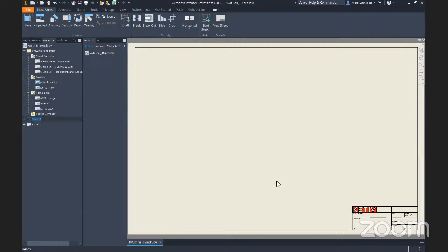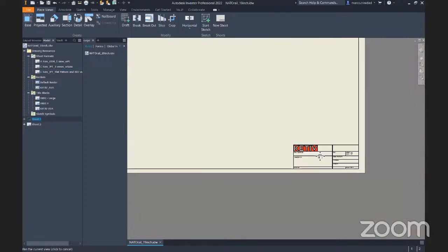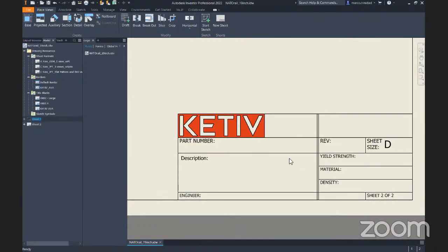If you have more than one, it does give you the option to select more. I just didn't have any more inside of mine, which is why they didn't show up. So it is going to be the first part you place. If you have multiple parts, it's going to define this based off of the first one.